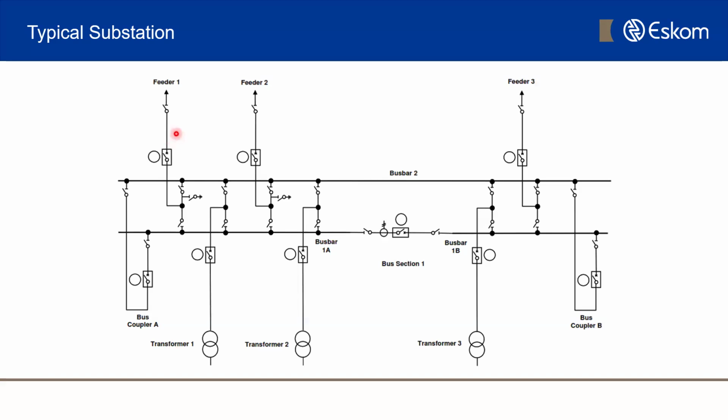So just for the purposes of discussion here, you will see that we have a circuit breaker. That's that circle with like a break in the network. And then those that are connecting the bus bars are usually the isolators. Okay. Those are the isolators there. We will be focusing on where faults are created in this system. So I just needed you to understand that you have isolators or disconnectors, circuit breaker, and then transformers. And all of these are connected by the bus bars.